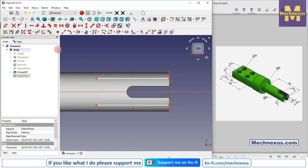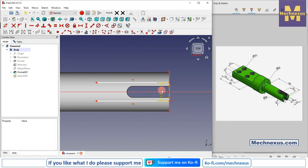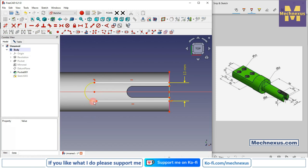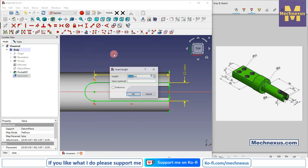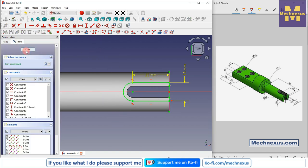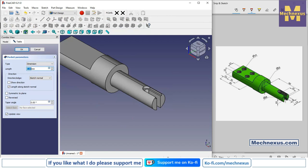and first thing I will give the vertical dimension of 13 mm and select a 3-point arc and create an arc and add the tangency, tangent, and select horizontal dimension and provide it a dimension of 25, and now we will close it, and now select the sketch, click on Extrude Cut and provide the cut of 9 mm,